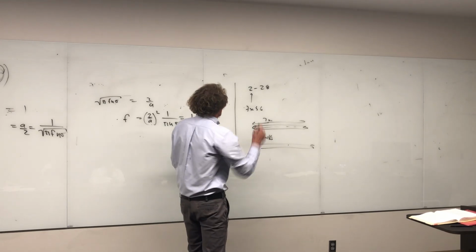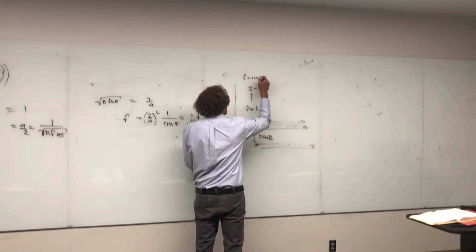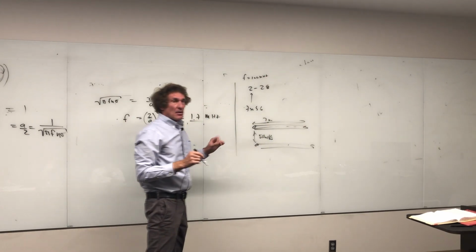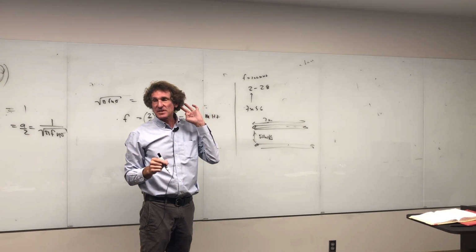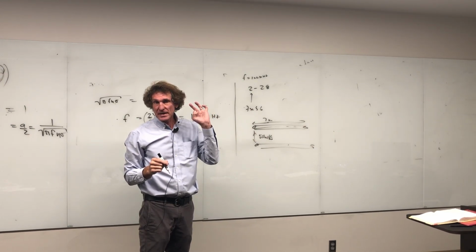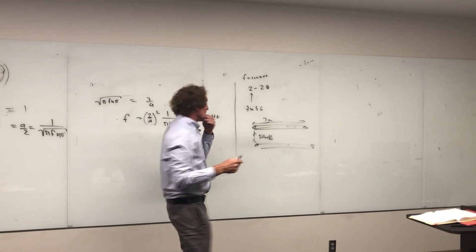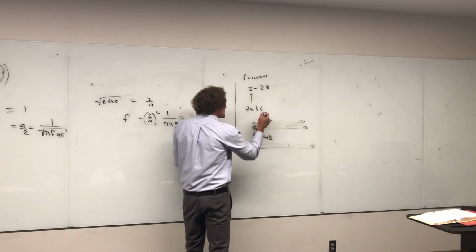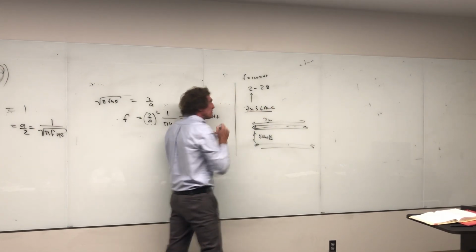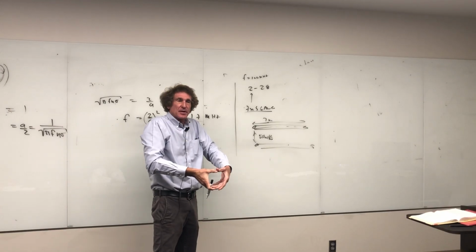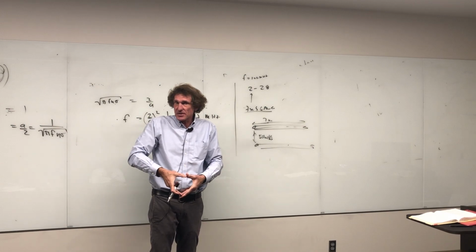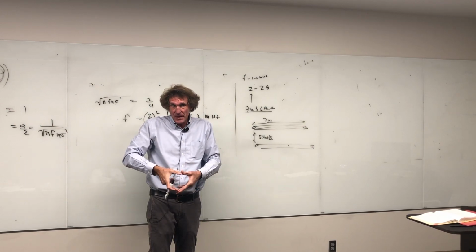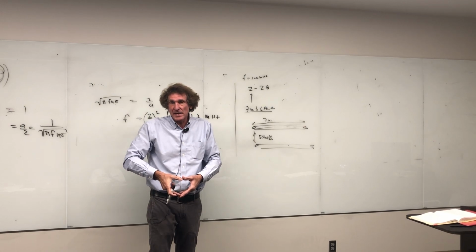Yeah, 100 megahertz. All right, so we have a frequency of 100 megahertz here. And now the next thing we have to do is take a look at what the radius is of a single wire. We're going to get the DC resistance, the AC resistance of that. So first things first, these are 36 AWG wires. There's 7 of them. They're 7 by 36. They're bundled together in a bundle that has the dimensions of a 28 gauge radius. So they got 36 gauge wires, but they bundle 7 of them, and that'll fit inside the housing for a 28 gauge wire. Got me on that one? That's the only thing it means.